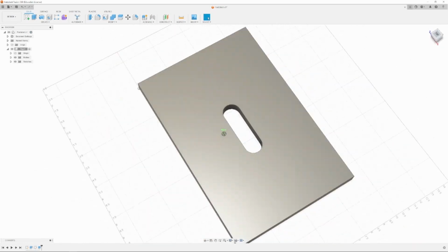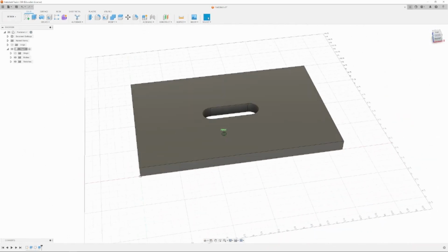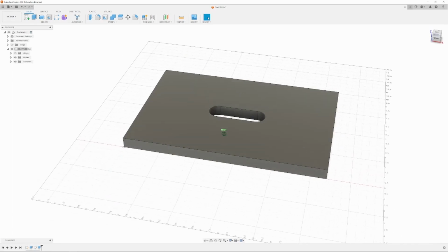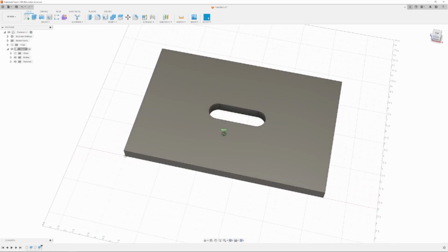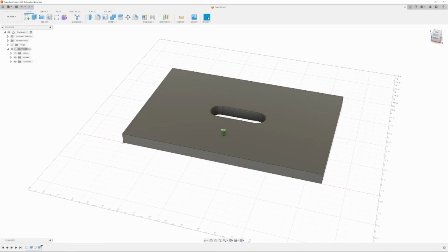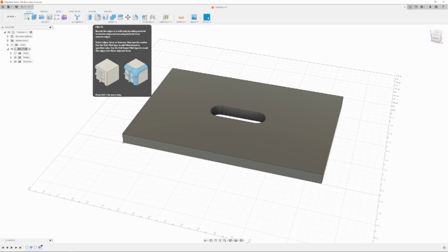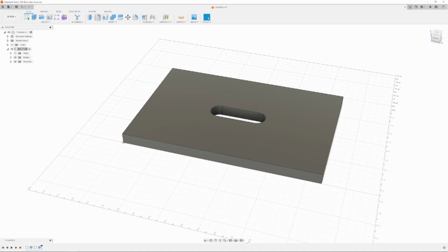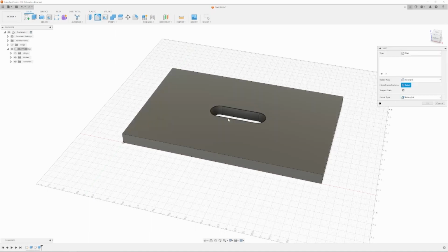If you've watched my SketchUp video, this is all we would do at the top, but Fusion 360 makes it a little bit easier to round over the corners, by applying a fillet option. So we're going to do that now. So up on the top here we have the fillet tool, which is hotkey F. If you click on that, we can start selecting the edges, and I'm just going to select them all, just clicking one at a time. You don't even have to hold shift or anything, you just click them.